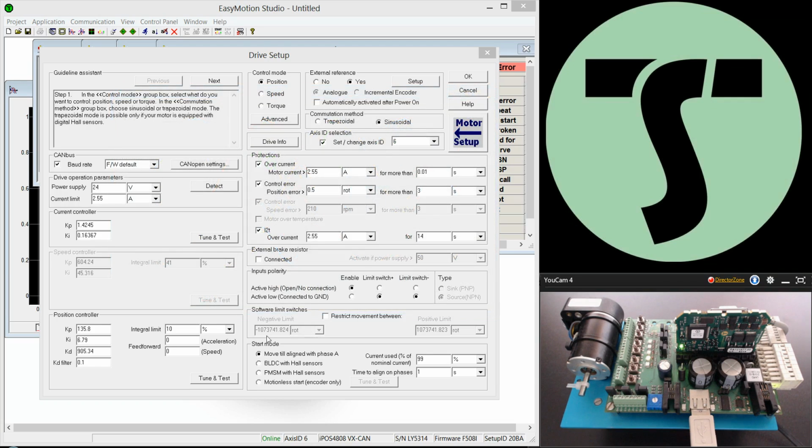The notion of start mode is given by the relative aspect of the incremental encoder used on this template. The digital Hall sensors, which are carefully placed and calibrated by the motor manufacturer, work as absolute sensors over one electrical rotation. This is the reason why when trapezoidal mode is selected, there is absolutely no start mode option at all.